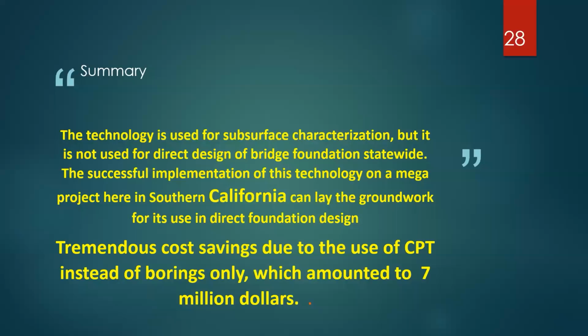So in summary, this technology was used for subsurface characterization, but this technology is not typically used for direct design of bridge foundations statewide in California. What basically made this project unique was that it was a successful implementation of this technology on a mega project in Southern California. And it can lay the groundwork for the use of direct foundation design using CPT for other projects coming up. It had a tremendous cost saving due to the use of CPT instead of borings only, which amounted to an estimated $7 million for this project. So it was, in my opinion, a tremendous saving for this project.